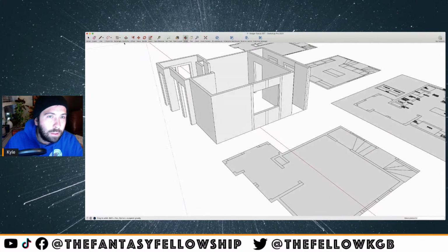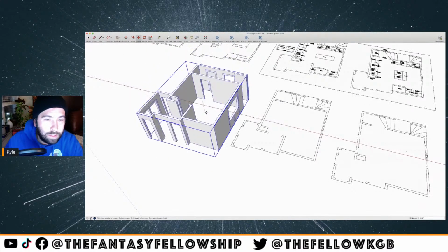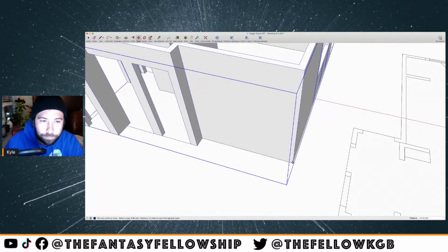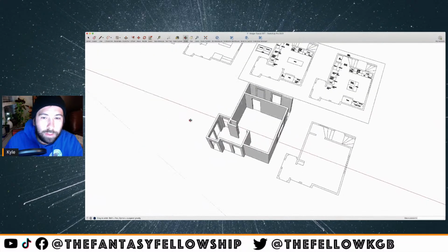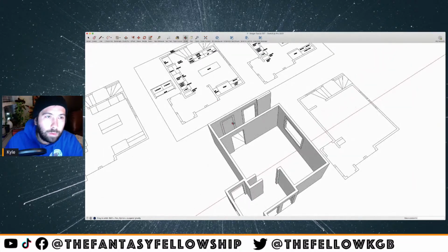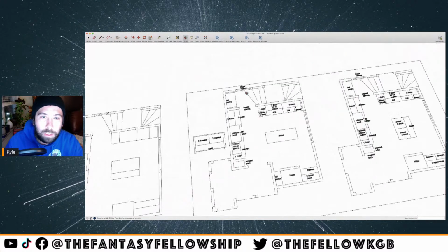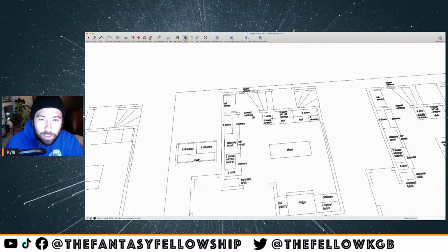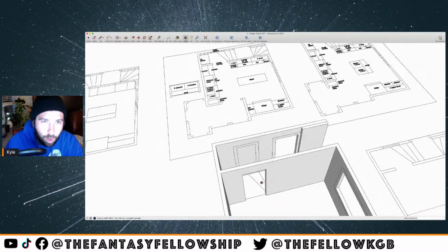We'll clean up some of those lines later, but this is its own group, and it's the walls. So I'm going to take the walls and land them on top of my model. And from here, this is where it gets kind of fun, because now you have this 3D room, and over here we can start to take some of the notes she's got going on. It looks like she wrote in a bigger window here, so I'll double check those sizes. She went with a drywall opening here, so you see there's no casing on this door. That's a drywall opening.